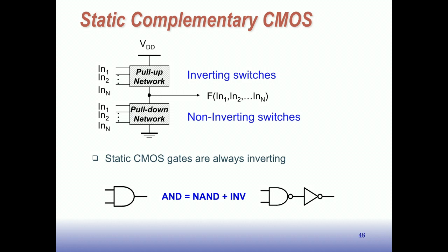And so if you need a function like AND, the way we build it is NAND followed by invert. And that's probably the best way to do it. Or do it all with NANDs and somehow push the bubbles around, and it'll kind of work out. A few inversions here and there don't really matter.